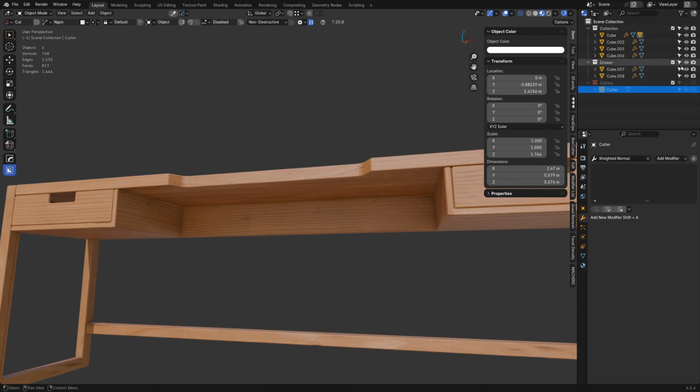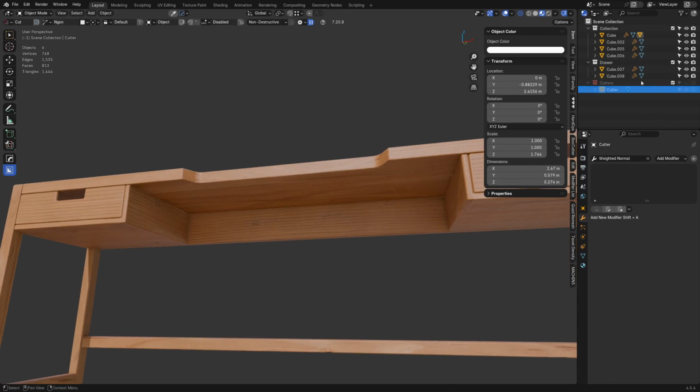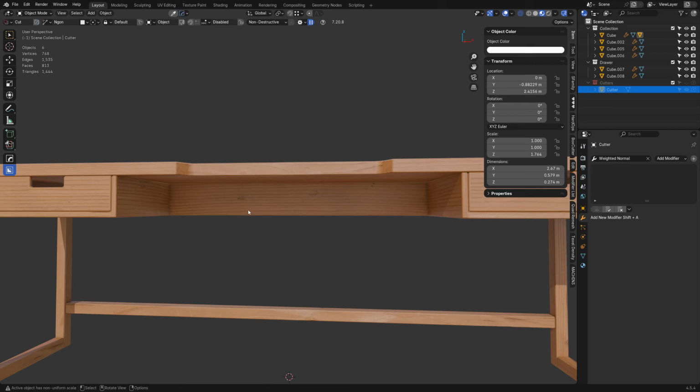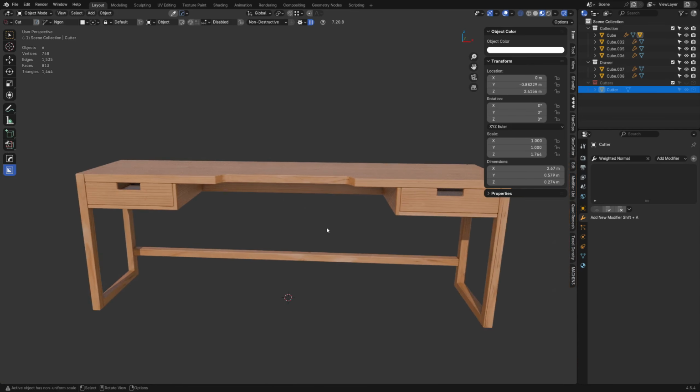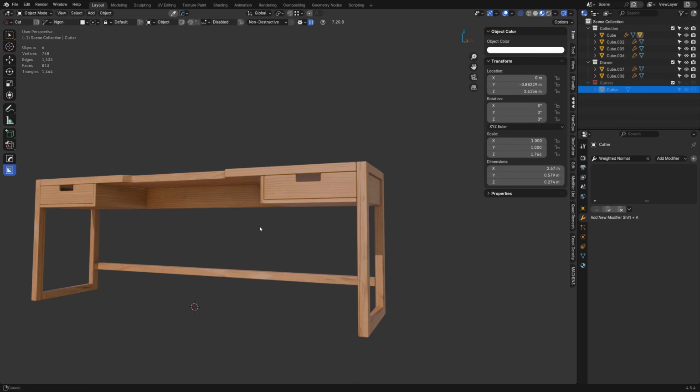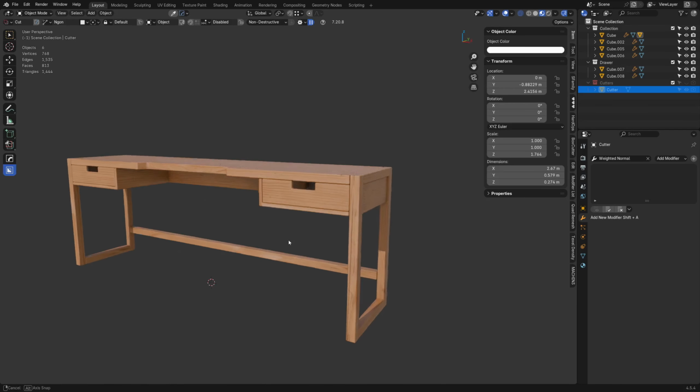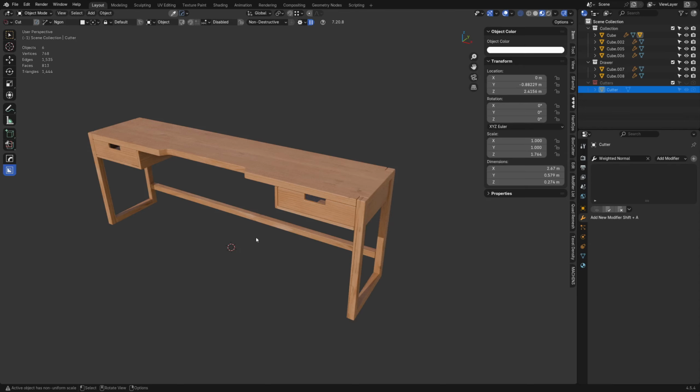So hide them in the outliner then. I think it only works in the outliner now, is what they said in the release video. You press 1, 2, or 3 over here, or Shift 1, 2, 3, and it'll hide and unhide. So you've got to hover your mouse in this window to do that. I'm pretty sure that's what it was, if I remember correctly. Which is actually kind of cool. That's not a bad idea, I think, for beginners, because that hiding collections thing is a little bit of a problem, right?